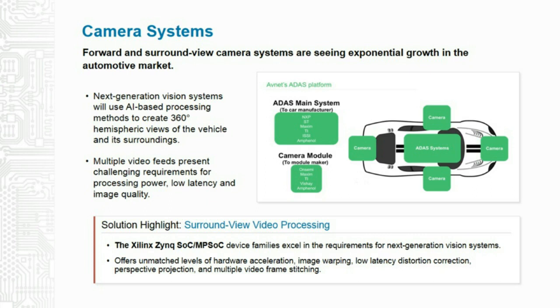If you have a color camera on the car, say on the windshield, the car can even tell when the traffic light goes green. It is not meant, however, for drag racing. Camera systems have issues. In rain, snow, fog, darkness, or a bright sun, their ability to detect what's going on does diminish. Because of these limitations, the data from image sensors is being combined with other sensors such as radar to provide a more robust and reliable data stream across a wider variety of conditions.